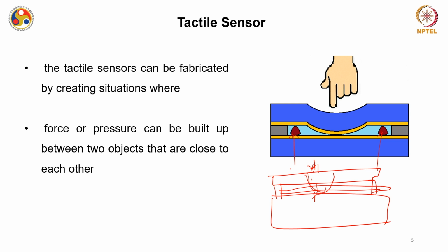When there is some electrical signal, say V, and it touches, it is creating some kind of short circuit. So, this voltage will be 0. This null value will suggest that it has been touched. When there is a voltage, it will suggest that there was no touch. Similarly, you can have other arrangements to have this touch or not touch feeling.